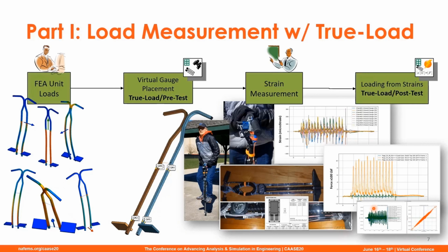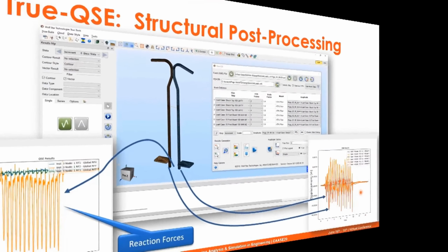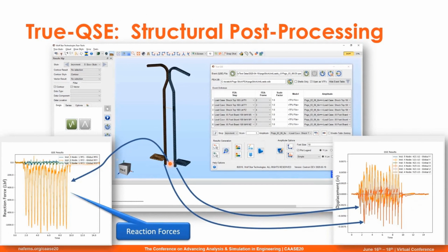And so that gives us confidence that these loads are correct. Now that we've got these loads, we're ready to pass those off to Endurica, and we'll do that in a few minutes here. And then I can also go in and query where I had my reaction forces, my restraint, and I can pull out the reaction loads here.